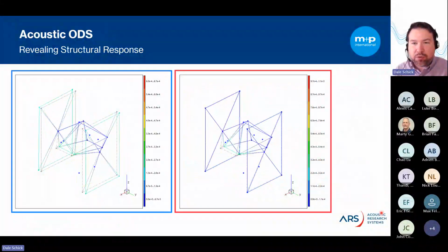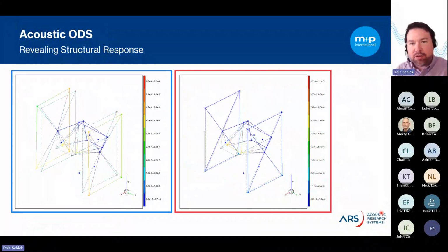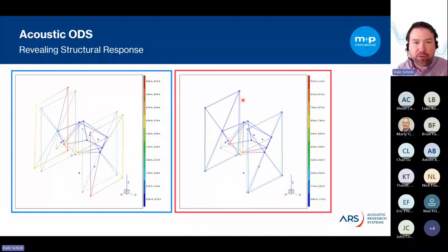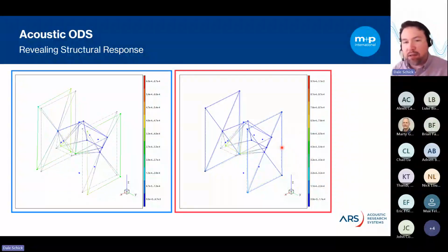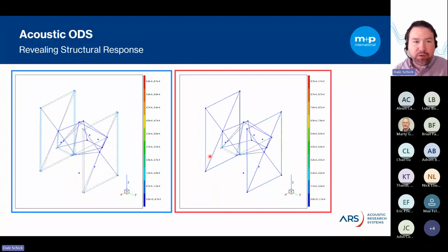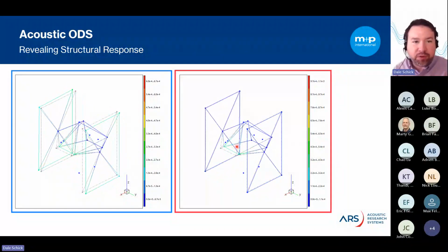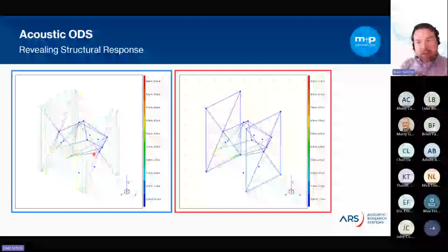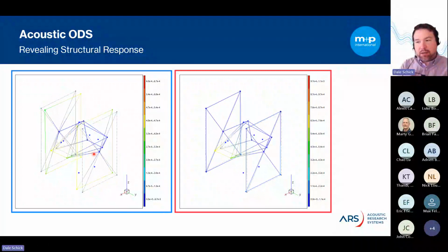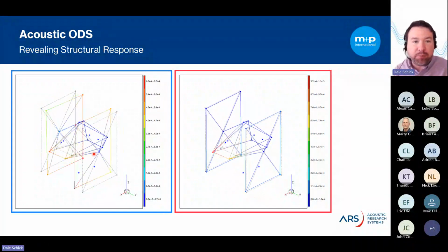Now, when we compare the two modes from one test to the other, you can see the muted mode only affects the solar arrays, right? So that means that the low frequency nodal spot or cold spot or destructive interference in the acoustic field is only affecting these two parts. Whereas you can see about the same deflection from the structural surface, which is a big cylinder, happening in both of them. So it's getting excited. It might even be generally excited by the entire broadband random nature of the acoustic field. But the solar arrays are the only ones affected.